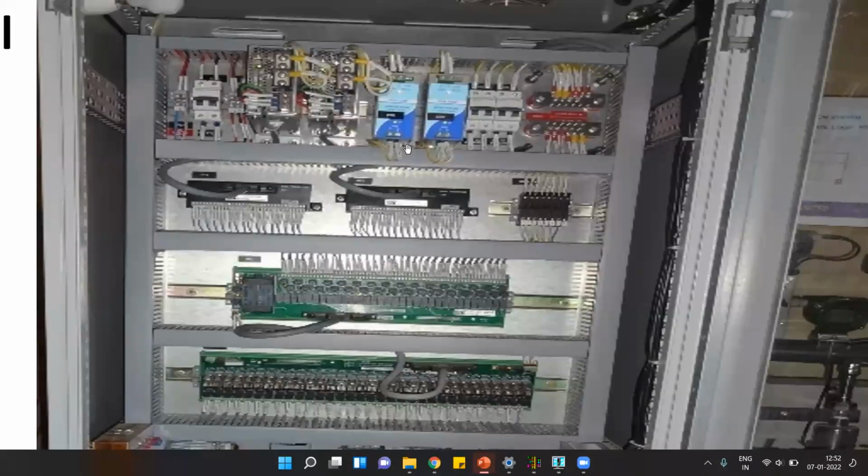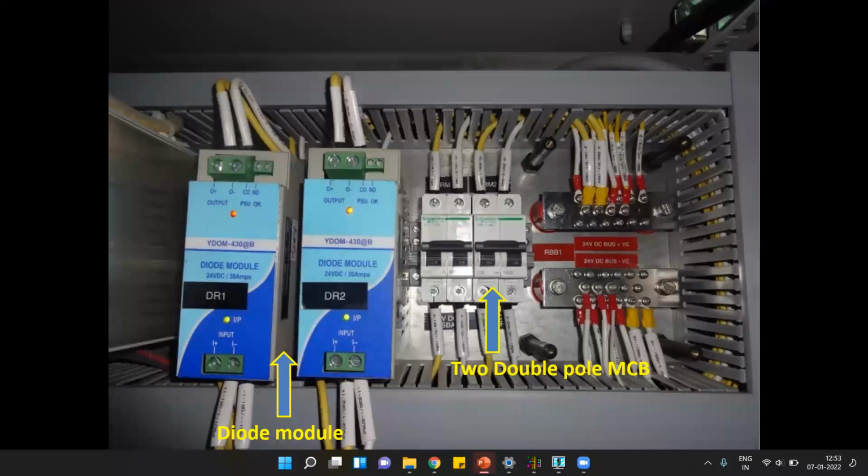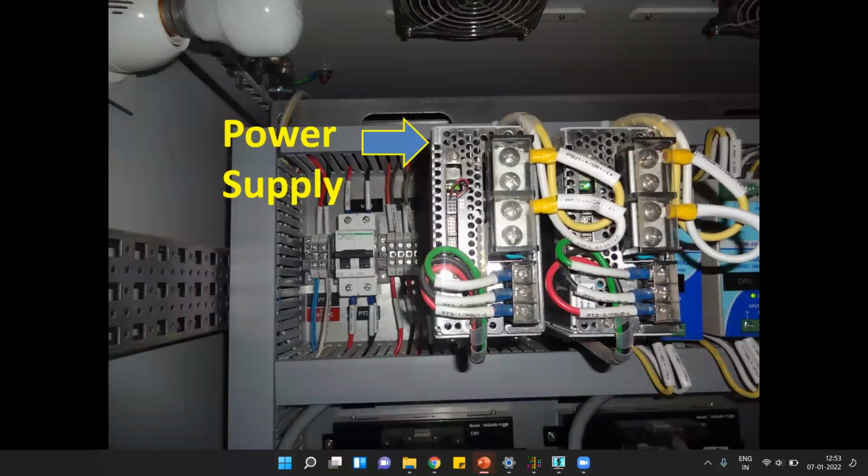So all the parts we will try to explain fast. This is the power supply which you can see on the DCS, which is used to convert the 230 to 24 volt, which is required for all the devices. Then there are the diode modules. So two diode modules for two power supplies. I think you understood what I meant to say.